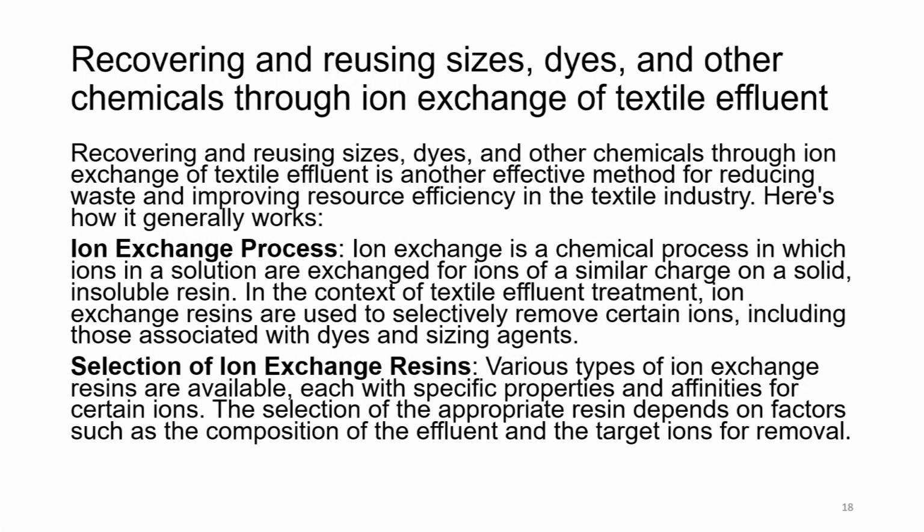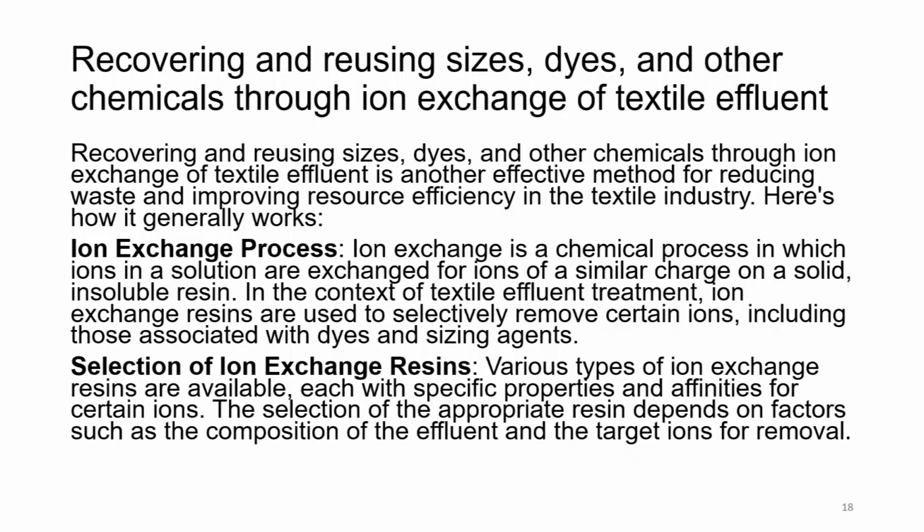Ion exchange process. We have already understood that in the past lectures, but we will re-look at it from the recovery and reusing aspect. Ion exchange is a chemical process in which ions in a solution are exchanged for ions of a similar charge on a solid insoluble resin. In the context of textile effluent treatment, ion exchange resins are used to selectively remove certain ions, including those associated with dyes and sizing agents.